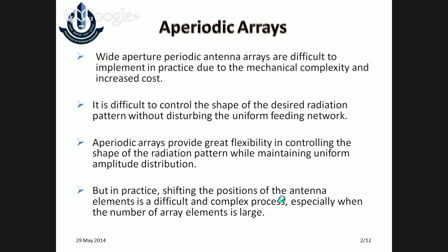In general, nowadays antenna arrays are widely used in communication systems, but controlling the radiation pattern in terms of the lowest side lobe level is one of the main important factors in designing any antenna array. For that, many techniques are there to decrease the side lobe levels by using amplitude distribution, phase distribution, and at the same time position optimization. But while dealing with large antenna arrays with a large number of elements, using amplitude distribution, the phase feeding complexity will be more. At that time, what will we do?